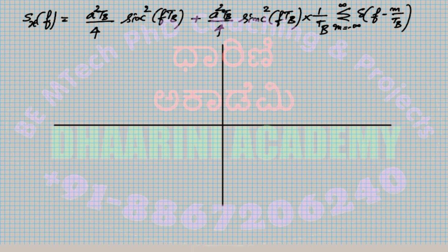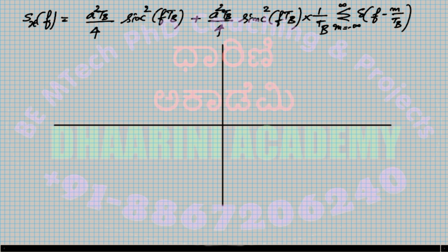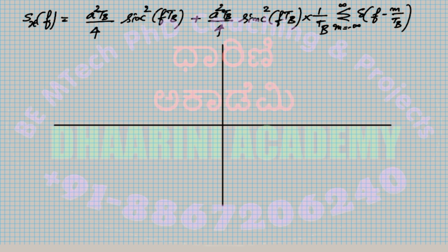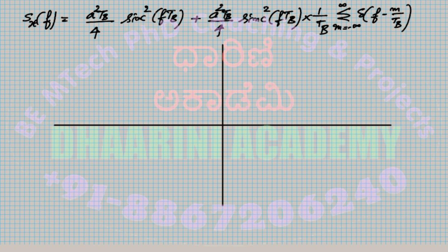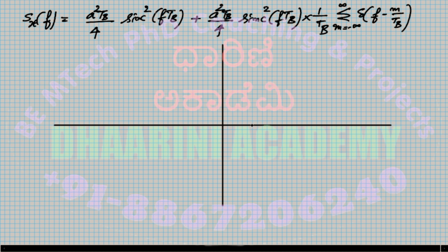So they are inverses of each other. Now if I know that my signal has a duration of tb, every symbol is of duration tb, then at tb, 2tb, 3tb, 4tb, the values are changing. This is what you know from the given signal. Now my question is, what should be their corresponding frequencies? It should be 1 by tb, double of that, 2 by tb, 3 by tb, and so on.